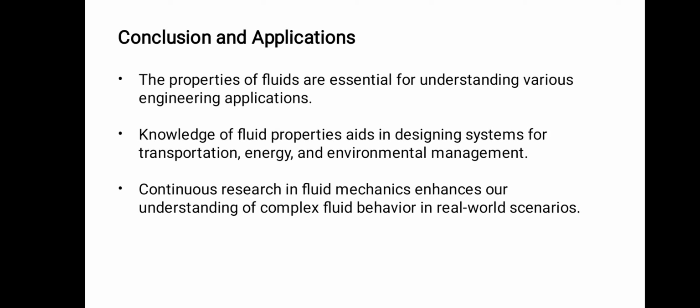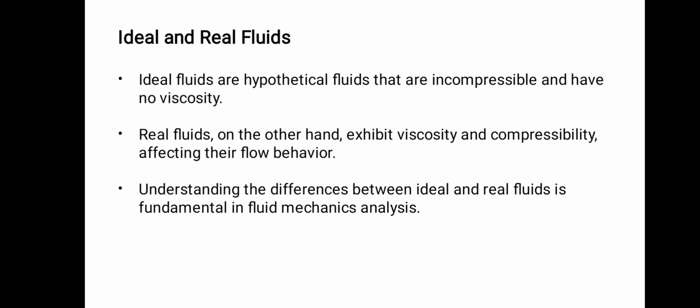And also there is another property like specific gravity. Specific gravity is defined as the ratio of the density of the fluid which we want to measure divided by the standard density. Based on the value of specific gravity, we can determine whether the object will sink or float. If the specific gravity value is less than 1, the object will float. If the specific gravity value is greater than 1, the object will sink. This specific gravity is one of the important properties in fluid flow behavior.